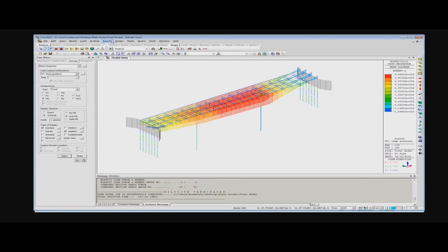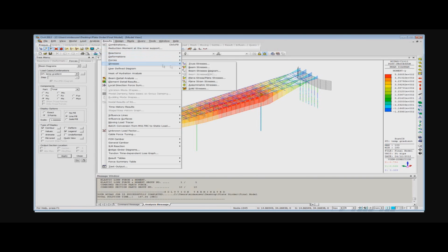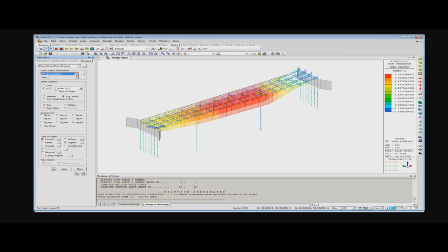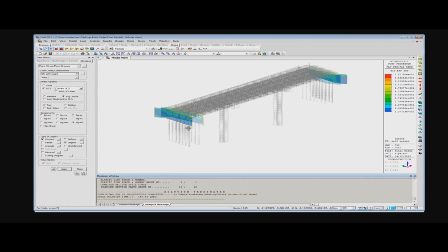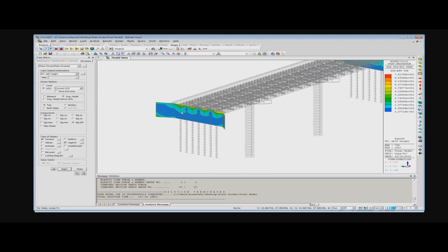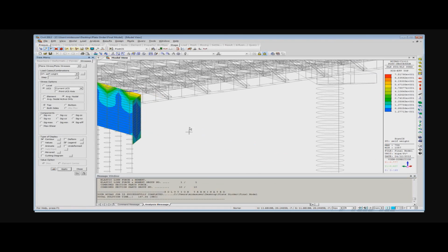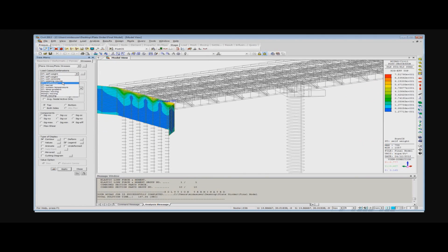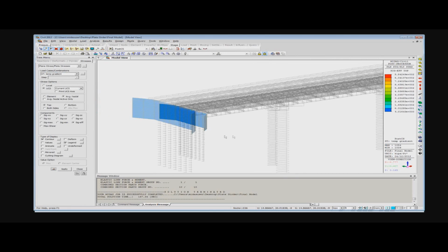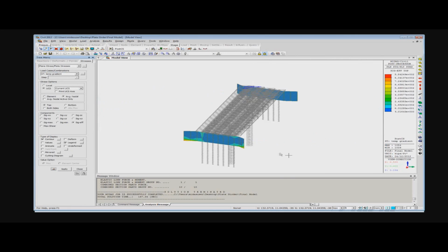not deformed form. Okay, now to get the stresses on the abutments, we go to the result, and then stresses, and then plane. Just go for the self weight and check that. Okay, now you see that the other elements are gray, so it means that they are not activated and they are not plane, but you can see the stress contour on the abutment. And you can change it to see the different load cases on them. Different load results.